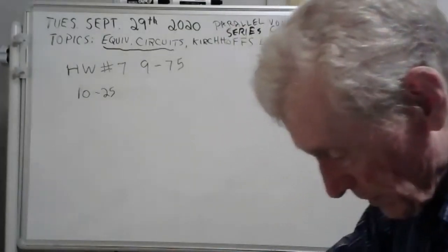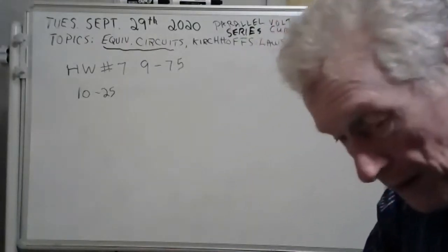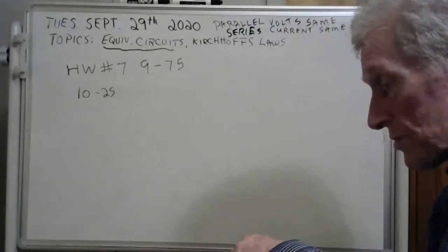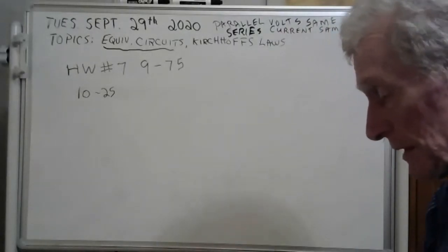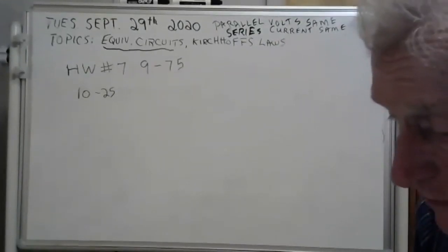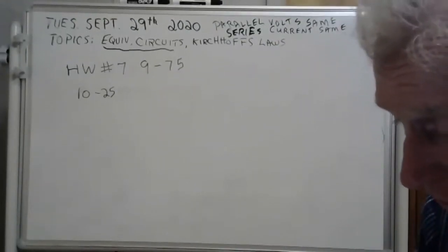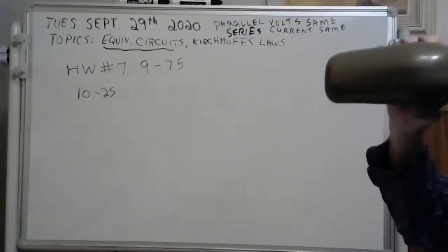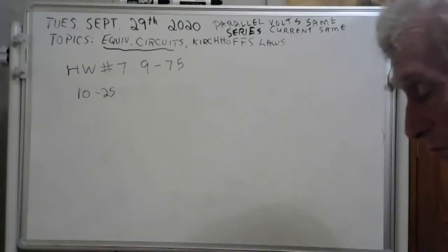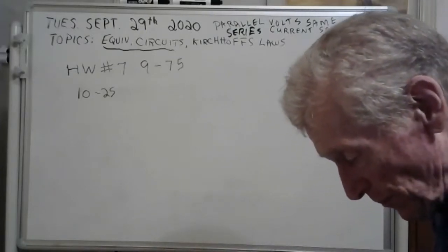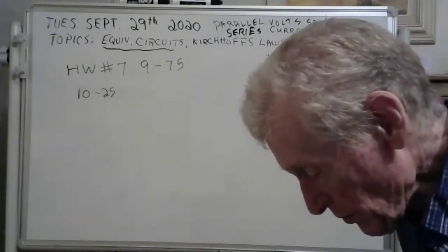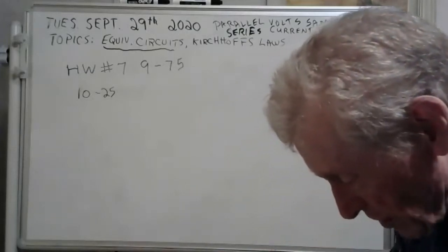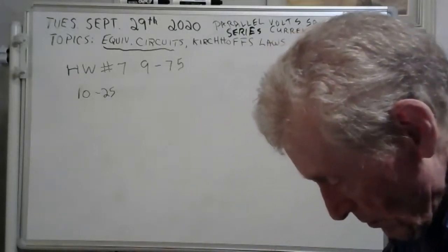We have a 12-volt EMF automobile battery. And I explained what that means. The 12 volts EMF. See, that would be the voltage if your battery didn't have any current, if it wasn't connected to anything. If you just put a voltmeter on it, that's what it would say. But it has a terminal voltage of 16 volts when it's being charged by a current of 10 amps.